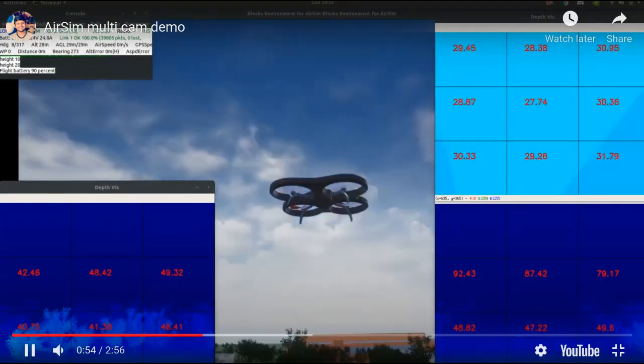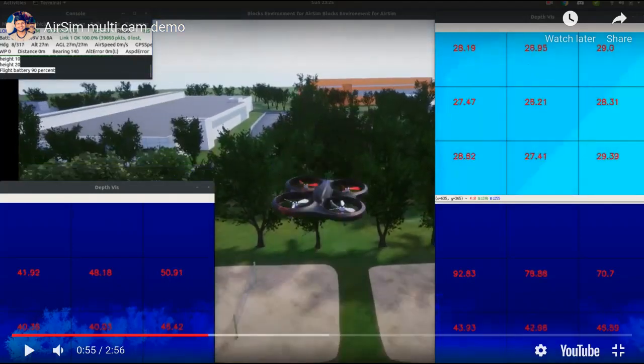This is again something that I really want to work on in the future: have the camera pointed downwards and be able to detect terrain much before the copter is on top of it. Right now we have a downward-facing rangefinder, and when the vehicle is on top of that terrain, that's when we figure out if we have to climb or descend.